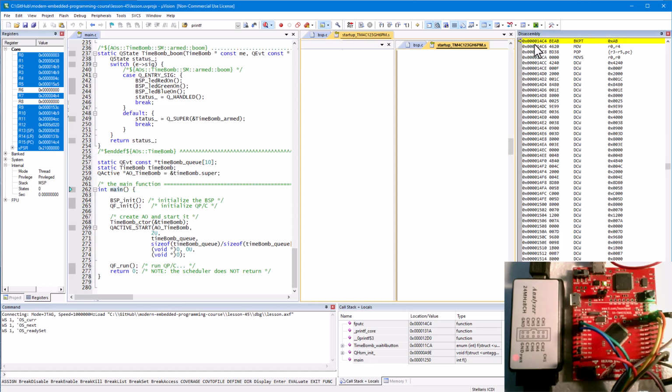But when you attempt to run the code, you still hit a hard-coded breakpoint, but this time in fputc, which is another C library function called from printf. So what's going on with these hard-coded breakpoints anyway? Well, it seems that the MicroLIB library provided with the Keil MicroVision toolset implements all standard functions, but the library cannot fully define hardware-specific functions. So instead of not defining such functions like fputc at all, the library apparently provides dummy implementations with hard-coded breakpoints.